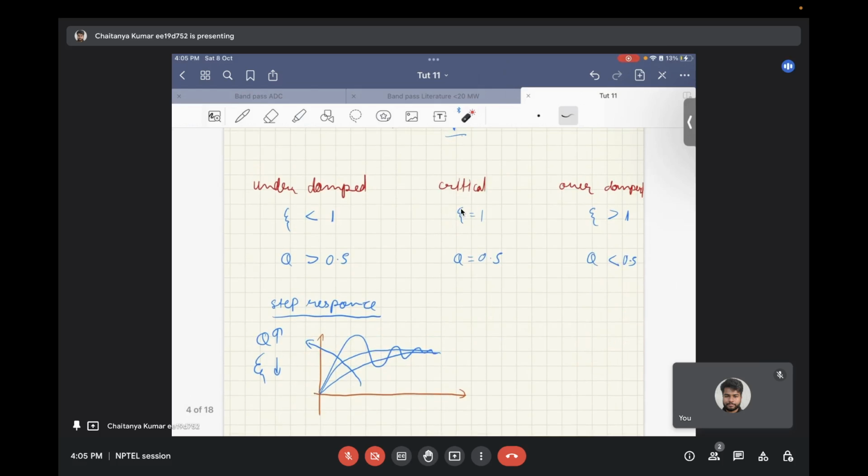So if you look at the step responses of these kinds of systems, this curve over here represents an overdamped system. This curve somewhere over here represents a critically damped system, and when you start seeing ringing in the response, that is an underdamped system. So in this direction, as we move, the quality factor starts increasing and zeta starts reducing. Now, for a quality factor of infinity and zeta equal to zero, we will see a sinusoidal curve with no damping at all.